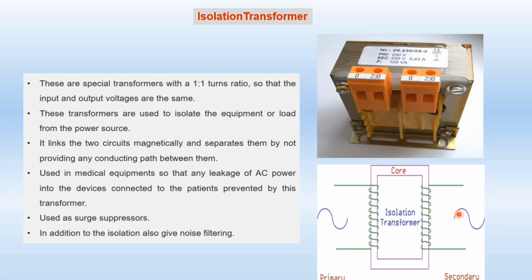And it is also used as a surge suppressor. So what is surge? Surge is a sudden rise in the input voltage or AC voltage. So whenever there is a sudden rise in the voltage, it will protect the load against it. And it also gives you noise filtering. So it will remove the noise coming from the source and it will protect the load.